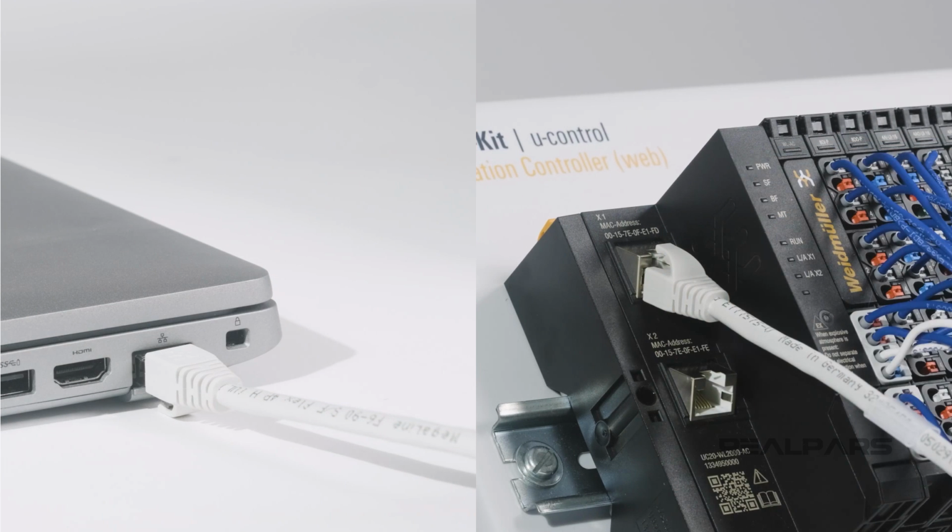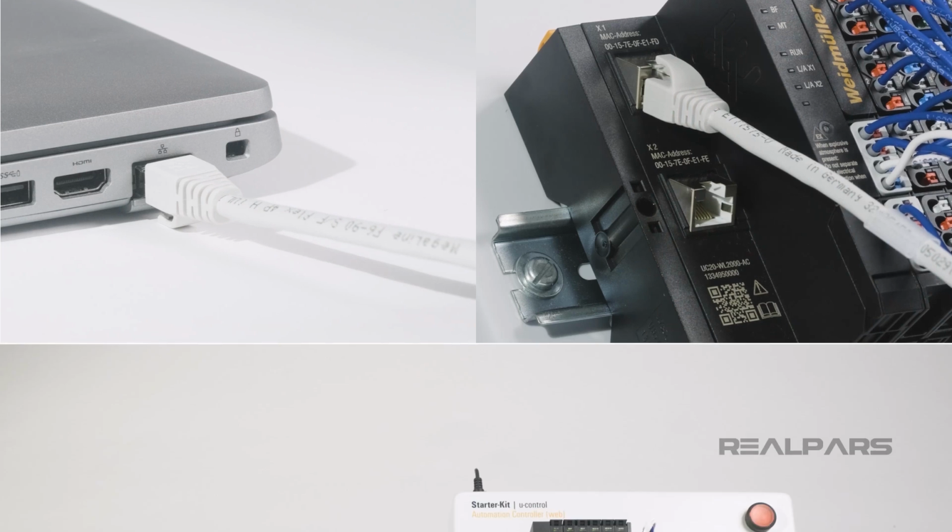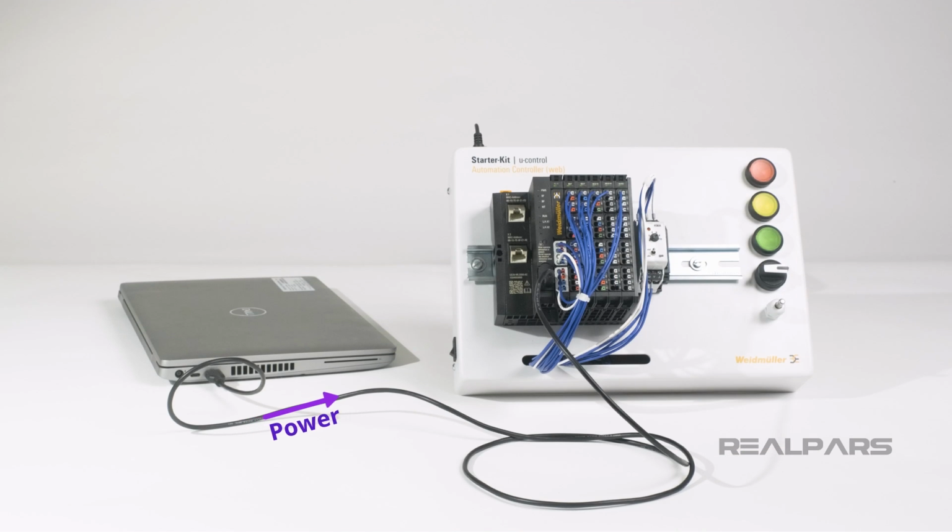The USB port on the U-Control controller is a service port, and in most situations, you will connect to your U-Control starter kit using one of the two Ethernet ports that are available on the controller instead of the USB port. However, an enormous advantage of connecting to the controller using the service port is that the USB connection supplies enough power to power the controller. This is a very useful feature when doing benchtop testing or development without I/O modules.